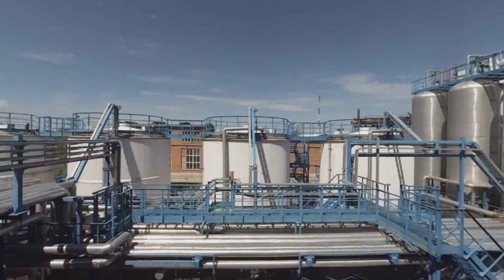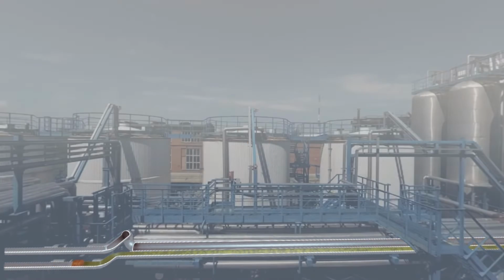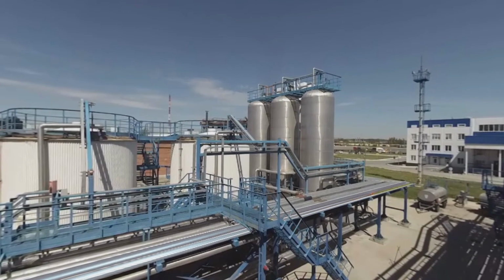After the manufacture process is finished with the previous cycle, the line can commence production of some other grades of oils. All pipes are equipped with self-cleaning systems. A piston moves inside the pipe using compressed air and collects residuals of the previously manufactured products from its walls.